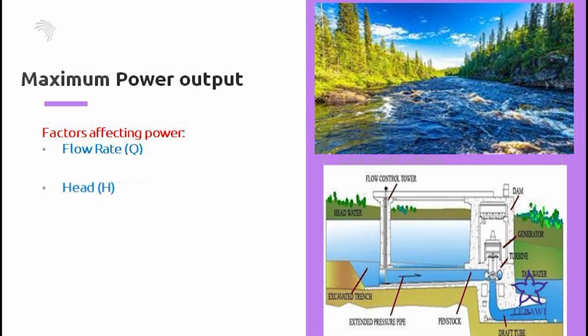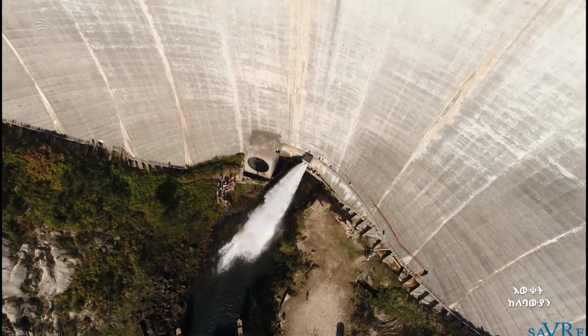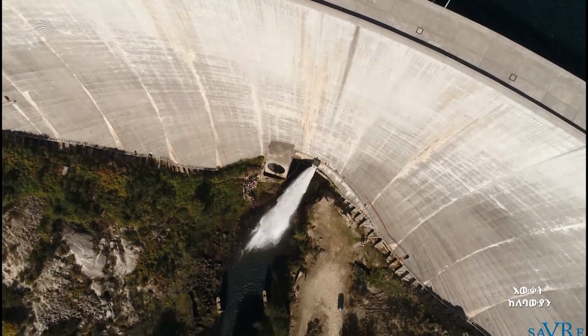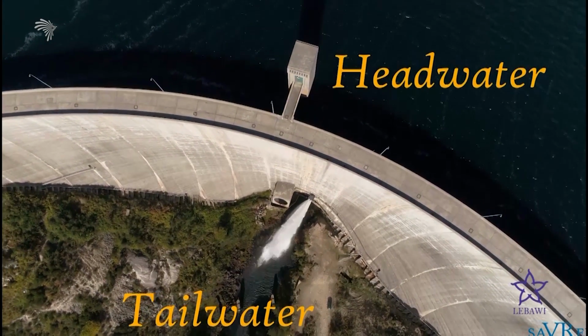The second factor is the head. By head, what we mean is the height from which the water falls. The farther the water falls, the more power it has. The higher the dam, the further the water falls, producing more hydroelectric power. Power production is also directly proportional to head. That is, water falling twice as far will produce twice as much electricity.